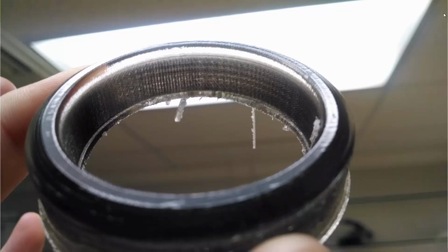On the PolyJet machine and the Connex machine, you do have some choices as to how dense your support material is. I chose the least dense support material here because I knew I was going to have to remove it from the threads. Now, it's very soft. The support material on the PolyJet side is kind of waxy, and so I was able to easily remove this using the water jet. We call it a water jet. It's really an electric pressure washer within an enclosed structure. I wish I had a picture of that, but we just shoot it with some water. It's a physical removal process, and it comes out looking something like this.